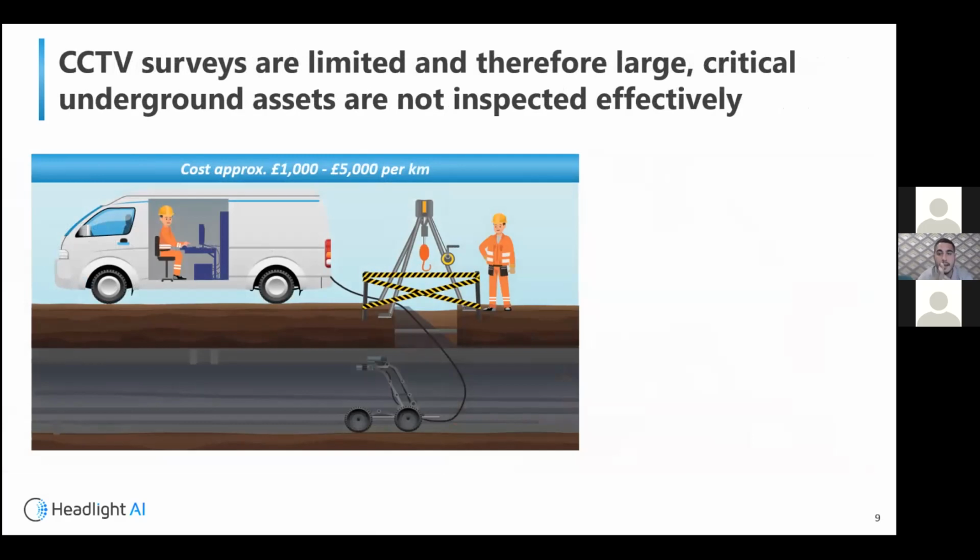One method that is commonly employed in the industry is to conduct inspections using CCTV surveys. This typically involves at least a two-person team, a CCTV robotic crawler system connected to a power line, and various safety equipment. It normally requires a NC2 confined spaces entry to place the robotic crawler into the structure. The crawler is then driven by one person who controls it from the van parked near the manhole access point. CCTV footage is recorded and defects noted manually using industry standard notation.